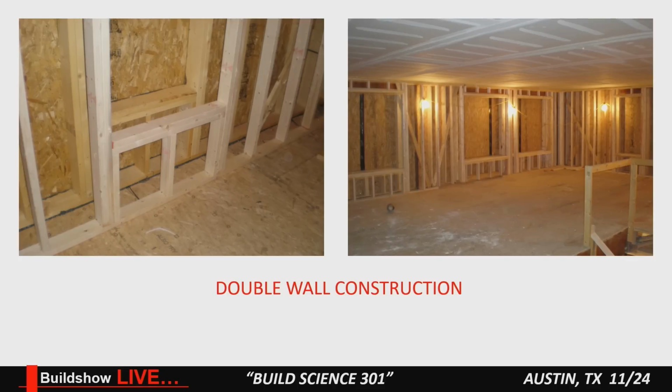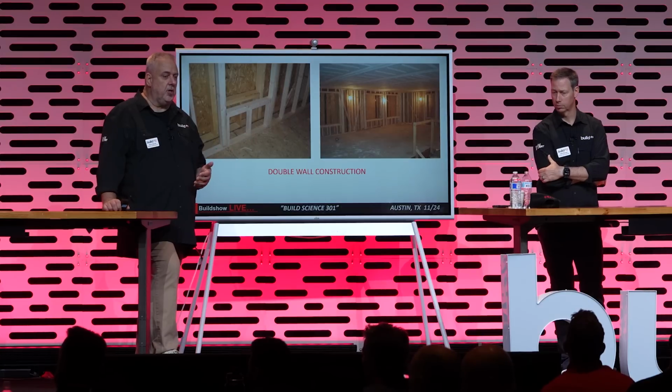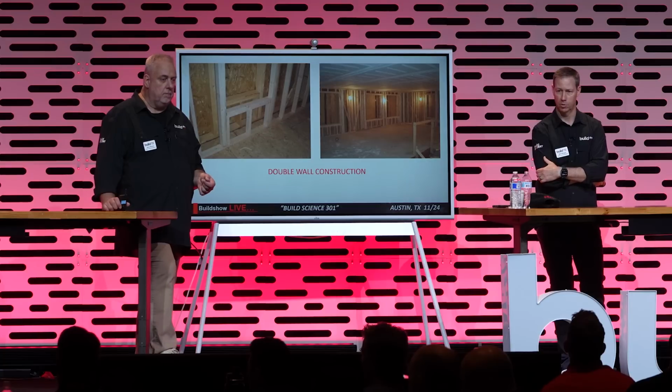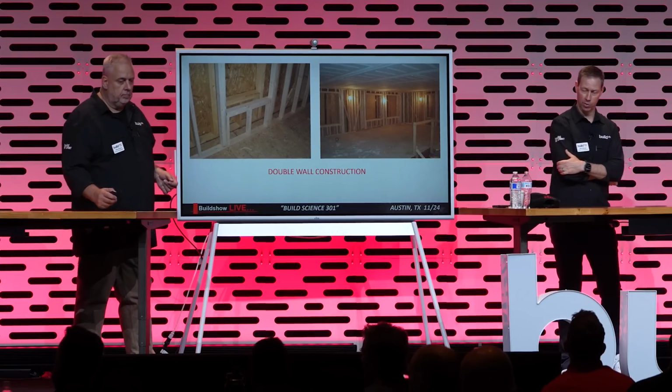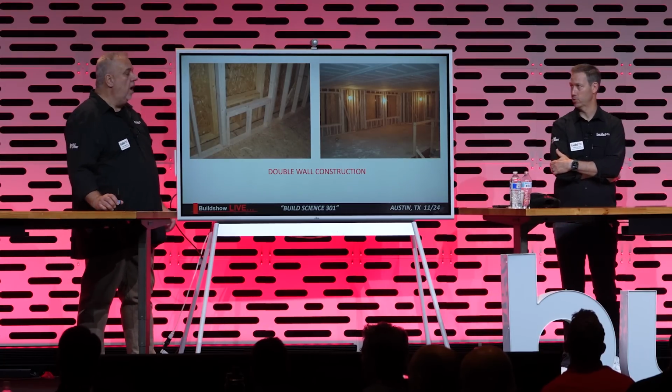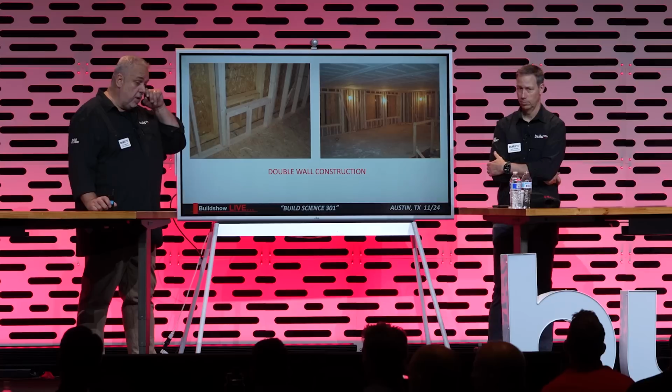Now the beauty of it, the picture on the right, notice we have some cross bracing. So the engineer said, we have this double wall, we should take advantage of it. We'll use 2x4s to help brace that outer wall. This one's literally on the ocean too. And we can brace that exterior wall and bump up our shear numbers by screwing 2x4s to the inside of the wall. Smart. And then the drywall's up because the interior walls are not framed, I'm assuming? The interior walls aren't framed, and that was part of our air barrier.